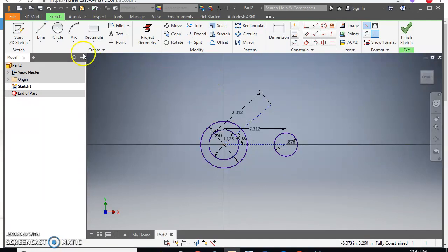So at the end of that line, we'll go ahead and put a circle up. Don't forget to turn off the construction line toggle. That'll be the same size circle as the last one, which would be, well, we typed in 0.438 for a radius, and then we multiplied that times 2 to get our diameter. There we go. Now, those two circles are connected with arcs.